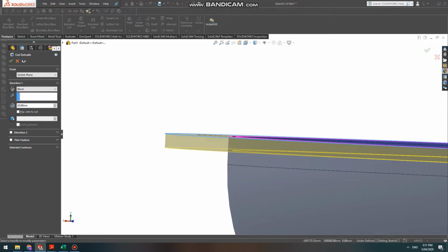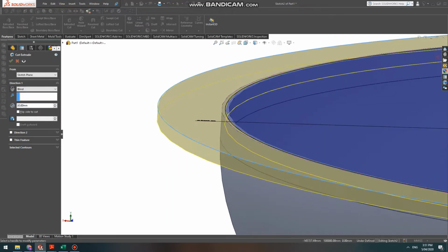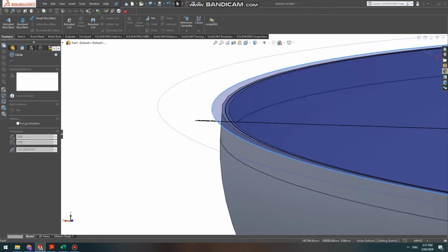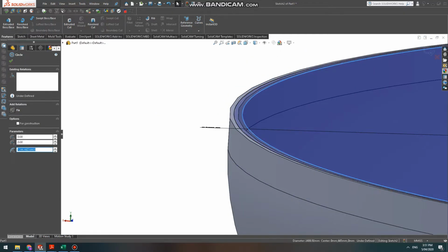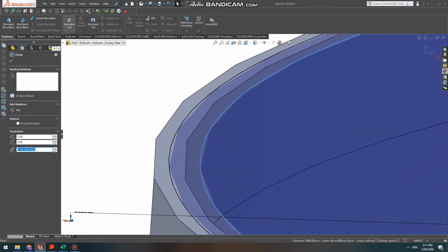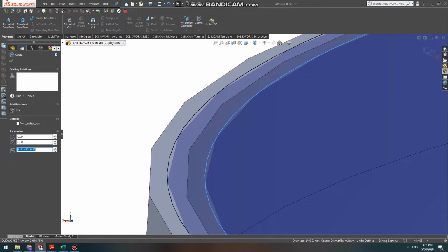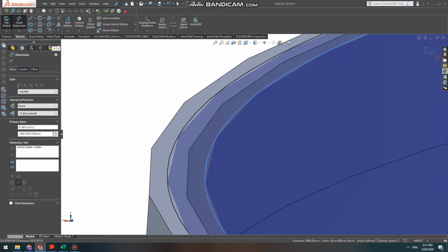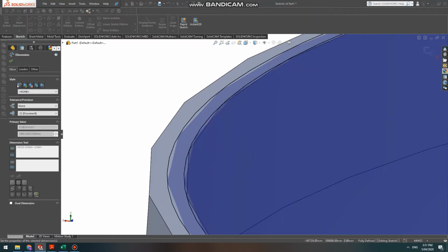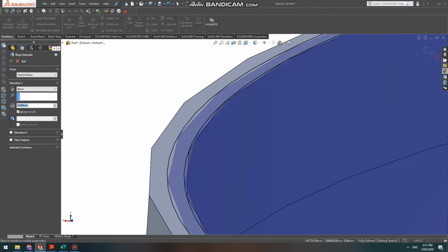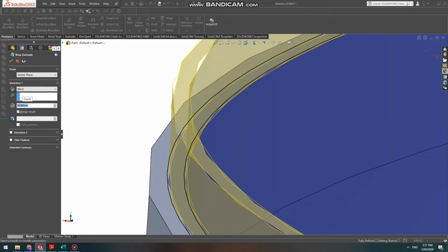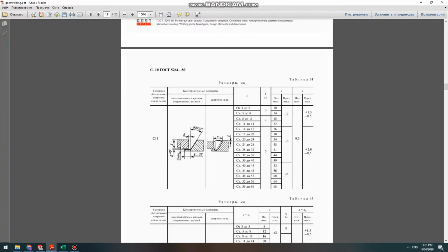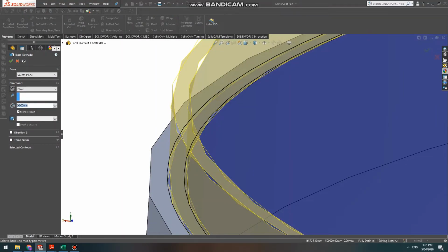However, that way it would reduce the height of it. So instead of extruding, we will do the opposite of it. So extrusion is better option in this case. We give it internal length of 2500, and we extrude it to 20 millimeters. 20 may be too much, since the standard says 8 to 20, so 15 will do.